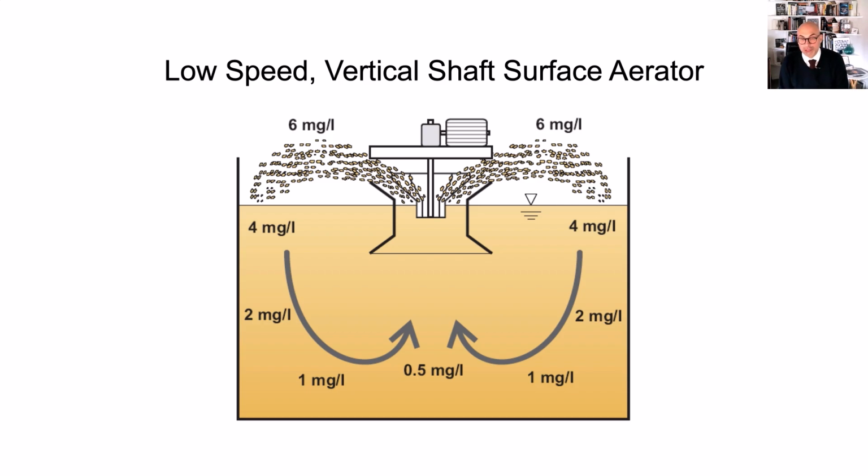The other problem you will have with this is cooling, because the droplets traveling in the air evaporate a lot of water, and that cools down the wastewater. So if you're in a winter climate, this may not be desirable. But if you're in a warm climate where you actually desire to cool down the water, otherwise you couldn't nitrify, this could be an option.